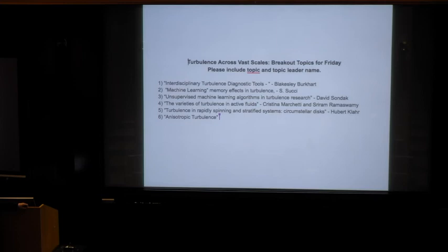So as one example, which is not the active part, but is elastic turbulence, the analogous parameter is the Weissenberg number. Right. Yeah. So there must be an analog. Sits against the convective term for the stress advection. So the point is having some scale separation and a nonlinear mechanism to feed the cascade somehow. And it doesn't have to be necessarily Reynolds. That is my very superficial reading after what I learned.